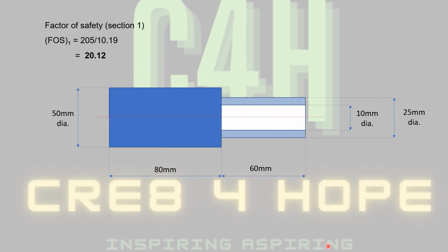We shouldn't forget that in this context, the stress will always be the same, because the stress is a function of the cross-sectional profile and the applied force. So the stress that we've calculated will not be compromised if we keep varying the Young's modulus. What's going to be affected is the strain.